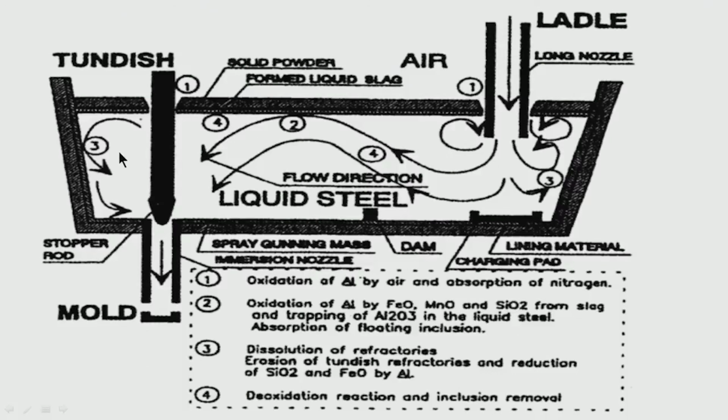There should not be too much dead volume. The liquid steel whatever is coming should not stay at a particular location. There should be a continuous flow, but the residence time should be more. So, this is very important. The dead volume should not be high. This is very important. So, this charging pad has to be there to protect this particular location where there is a possibility of impingement of the incoming liquid steel with the bottom at this location. So, these are important issues.